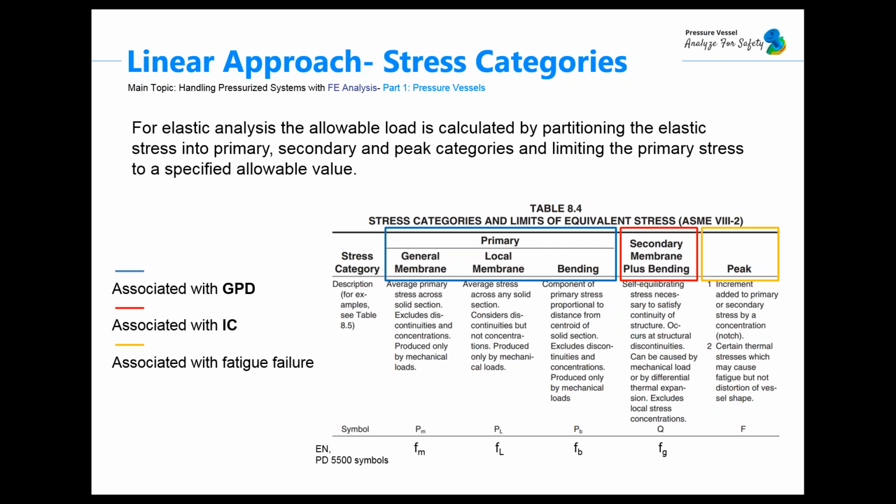And primary general stresses are characterized by not being self-limiting, which means that they are distributed within the structure so that no stress redistribution will occur as the result of yielding. An example of primary stress is the hoop stress within a pressure vessel induced by an inner pressure. By increasing the pressure, the stresses will increase until yielding. And there are 3 subcategories of primary stresses: general primary membrane stress, primary bending stresses, primary local membrane stresses.